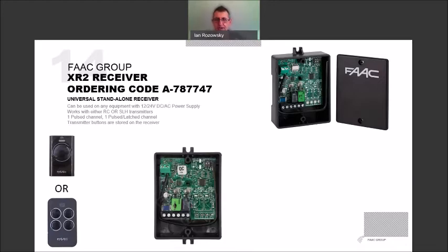So you have to go through a deletion process, which we'll cover at the end of the presentation, and delete the unit completely, which then sets it back to effectively factory defaults, and then you can learn your RC remote control. From there forward, that receiver becomes an RC receiver.